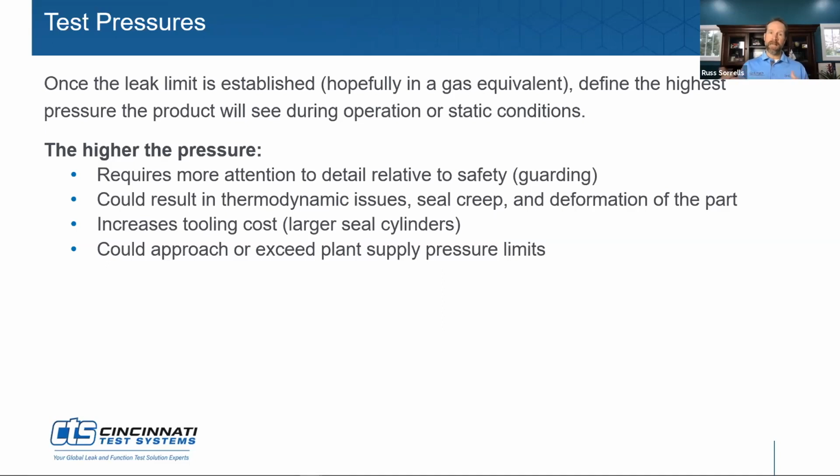The volume and the pressure are going to have an impact as it relates to the actual leak rate that you're going to be testing for. So that's why we like to see a flow as the accept/reject criteria.